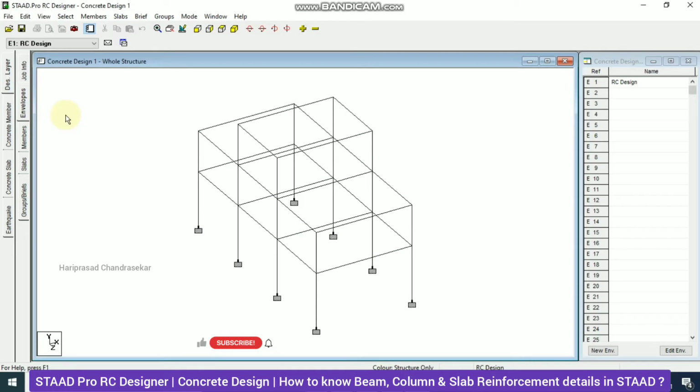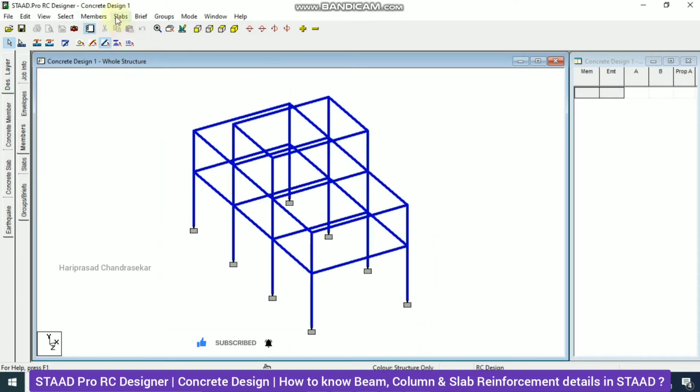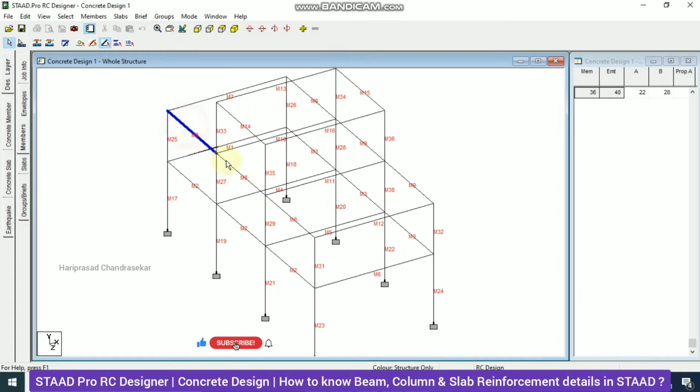Now based on the loads only, we will design our members. Now you can just click member. So select everything and then we can just go for members, auto form members. So why are we doing this? See, for example, here we have separate beams, but practically it is a single beam. That's why the numbers, see M8, M8, M8, will automatically become one single member. But columns are different and separated, M19, M17 like that. So that's why we are putting auto form members.